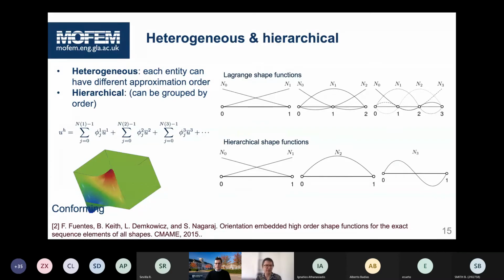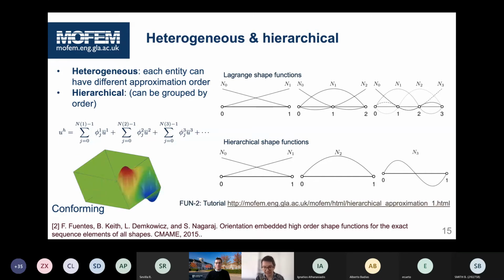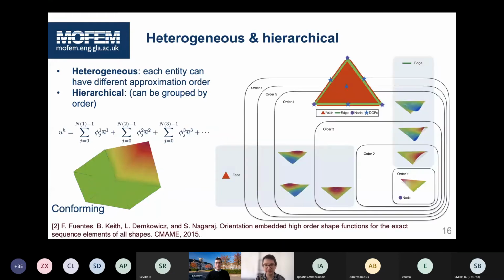In 2D, for example, it will look like the figure below. You can see that we have some base functions associated with nodes, edges, and faces at the end. About that, you can read in tutorial 2, Fundamentals 2, and follow that link. But in MoFEM, we are not only restricted to the hierarchical basis; we use Bernstein-Bezier polynomials as well for fast integration.